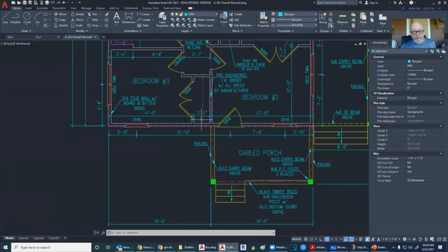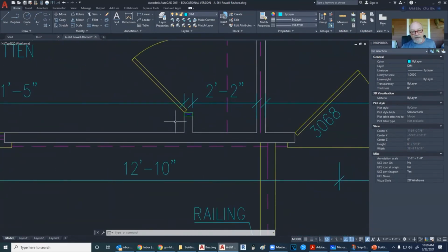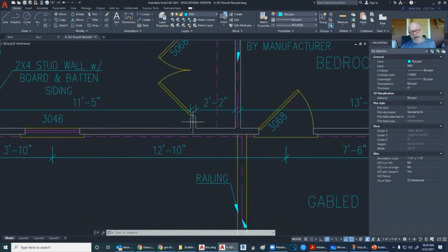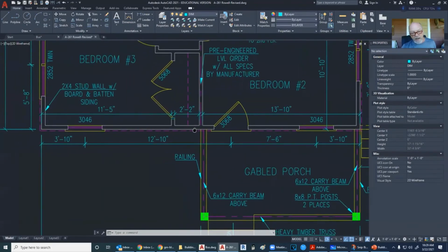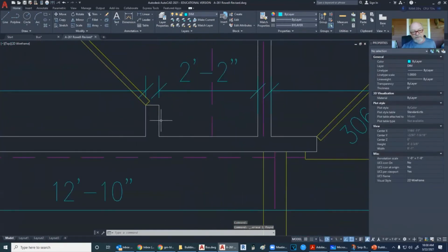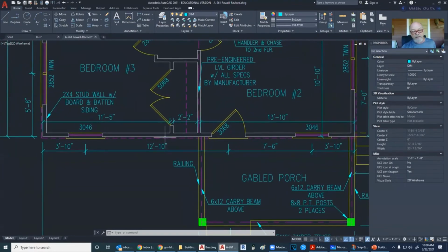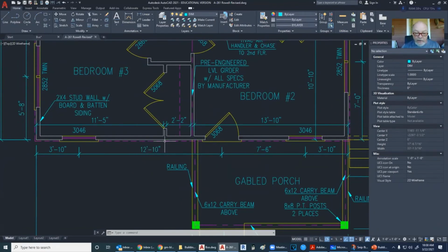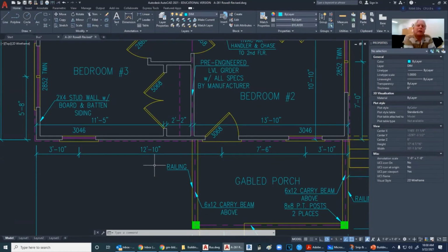So if I were to dimension with, let's say, a 1/2 inch sheetrock on this side and a 1/4 inch piece of paneling on this side, and then the homeowner comes in and changes that, well, I would never dimension to the finish, because this way I can put any finish I want on there. It doesn't matter if it's 6 inches of finish. I have my stud in place, and that's what the carpenter is going to start with. The same carpenter may not even be putting in the finish. Maybe he's just a good old boy framer. He does the frame, and he doesn't come back and put drywall, and drywall is usually done by a different discipline. Yeah, so we want to make sure that we dimension to our framing and not to any finish whatsoever.